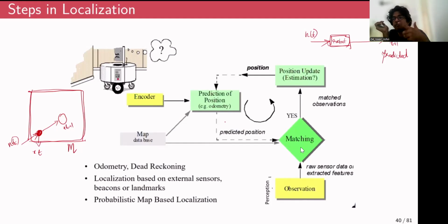If a wheel was slipping, or was not properly in contact with the ground, the motor would still be spinning, but the robot would not actually be moving. So there is a probability that the position predicted by the encoders could be different from the actual position of the robot. The actual position can only be obtained through the sensors.